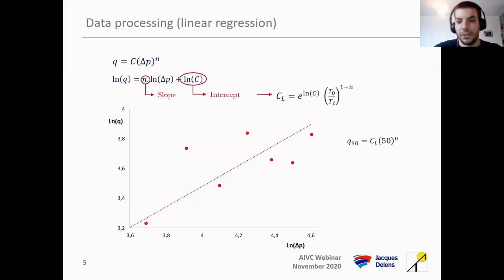Then I have the air leakage rate at 50 Pascal given by this formula. And when I report the test, I report the air leakage rate at 50 Pascal in pressurization, depressurization, and average, and the airflow exponent in pressurization and depressurization. I did all the tests with the 2 regression techniques Vitor told about in his presentation, the ordinary least squares and the weighted line of organic correlation, but in these results, it has no impact. So I will not go more in depth on those aspects in this presentation.